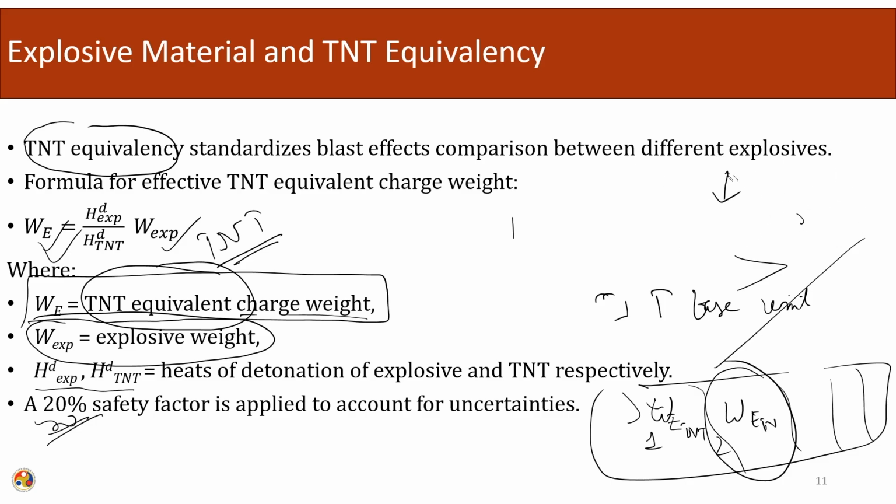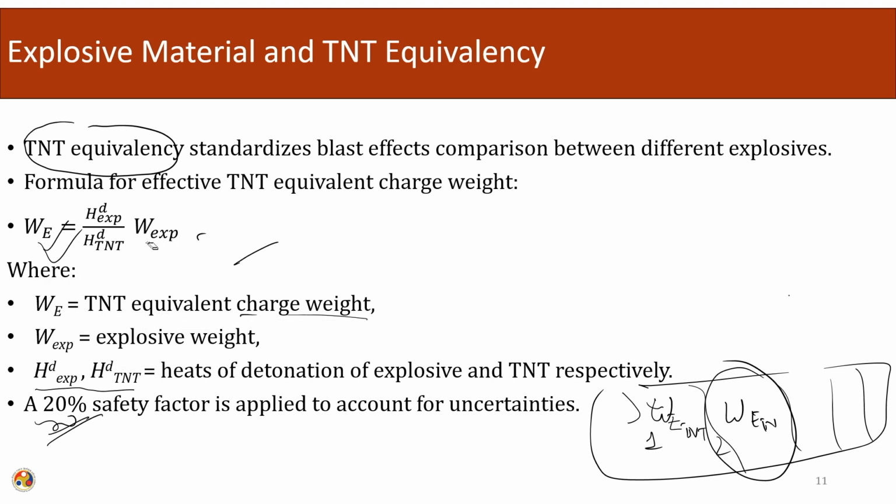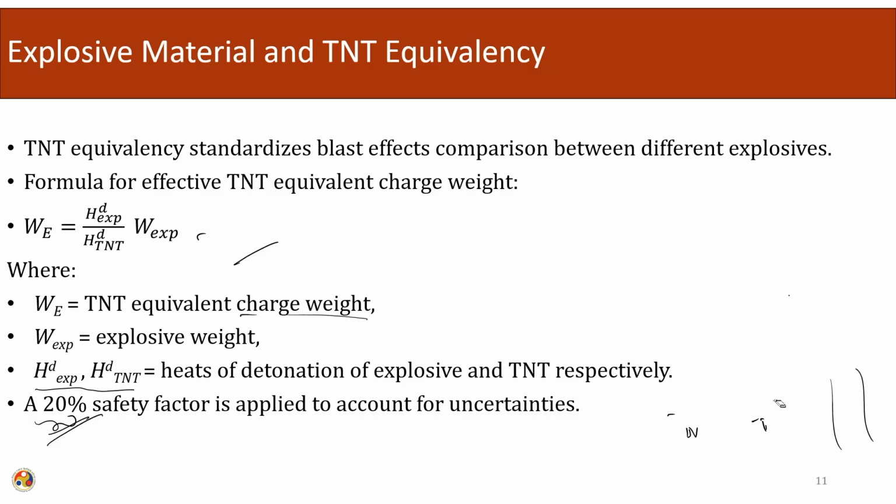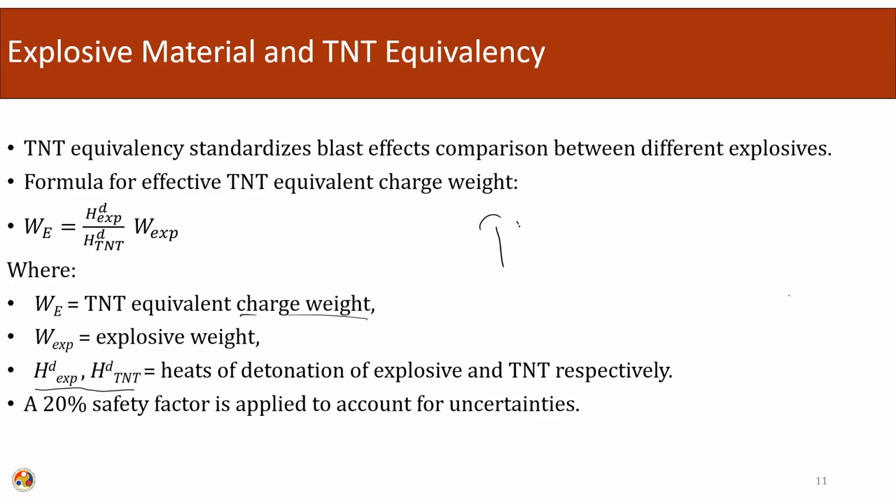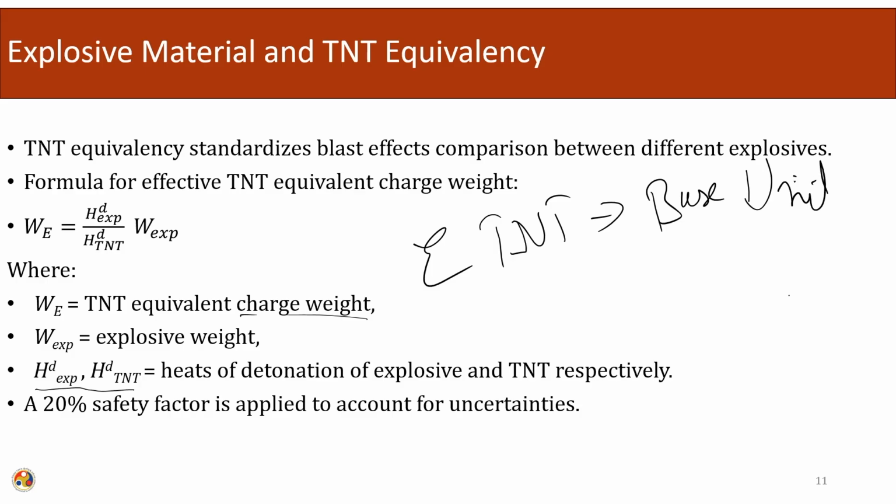Actually, any type of explosive can be used, handmade or otherwise produced, depending upon the requirement. But when we are doing the analysis, we will always convert them into an equivalent amount of TNT, depending upon their heat of detonation. So TNT equivalency, or equivalent amount of TNT, becomes our base unit in blast loading.